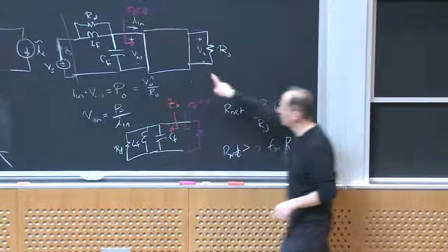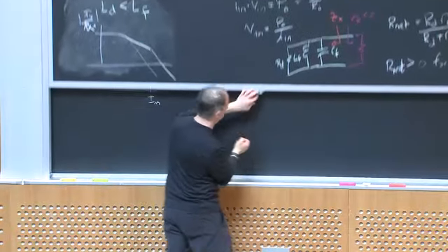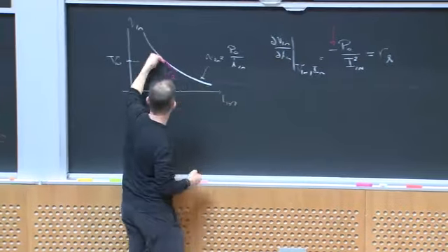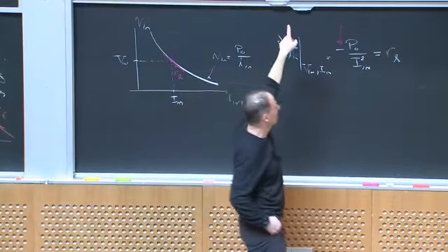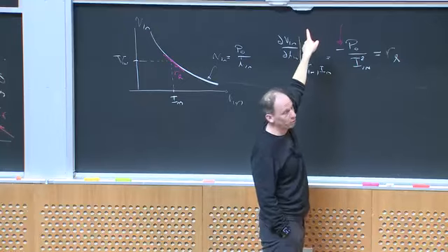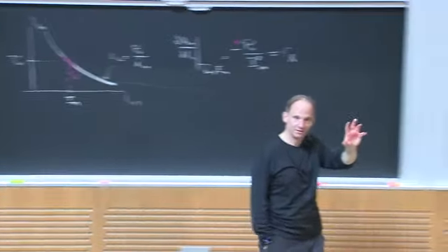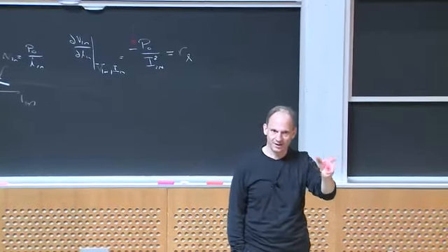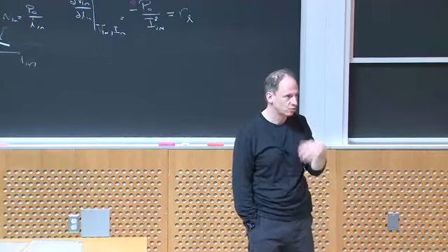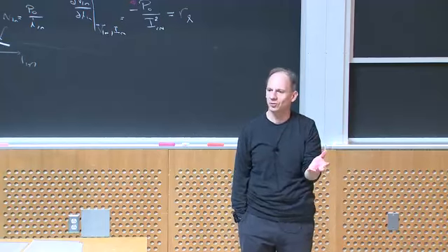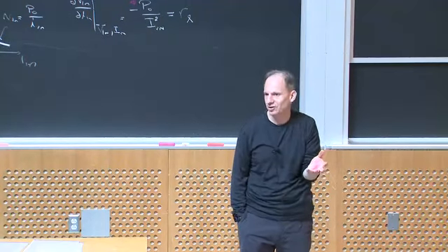So if I'm looking in here, and this slope is sort of minus 1 ohm, I'd better make sure RD is less than 1 ohm, otherwise this LCR stage is going to start to oscillate, right? And that's not going to be happy. And this is true in this instance, but it's true in a lot of other instances where you have to deal with these kind of self-regulating loads, as they just tend to destabilize your system.